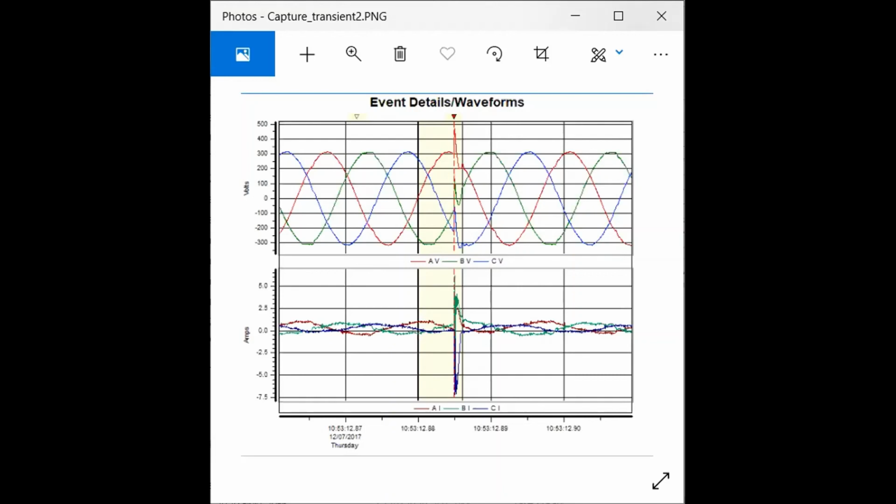And those PQ rules that you use to determine directivity for RMS events such as sags and swells, you can also use those same rules for subcycle events, current transients as well, as long as you have the instrumentation that is capable of capturing and recording that data. But getting back to this chart here, the concern here is the peak value of the voltage transient. Whether or not that peak value is going to cause something to misoperate or lock up.